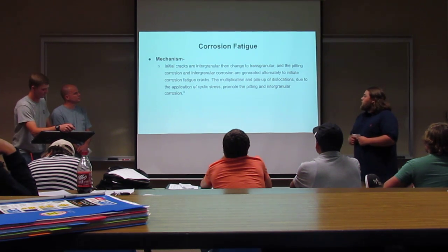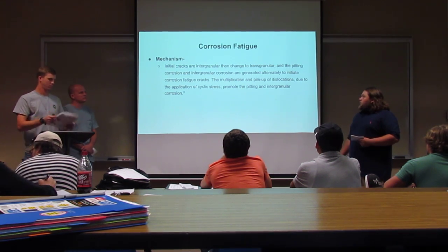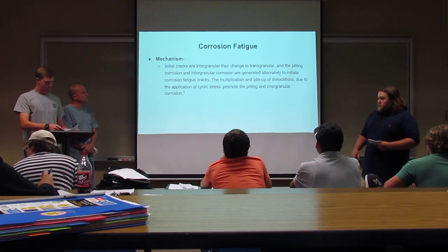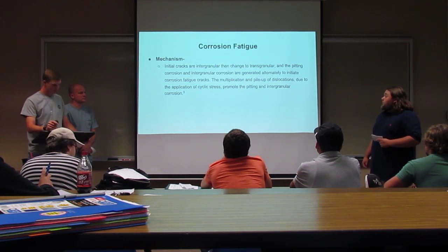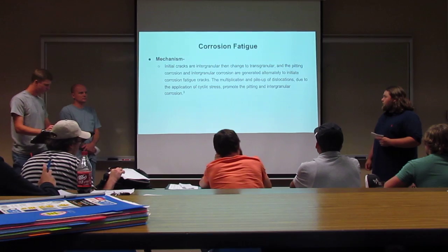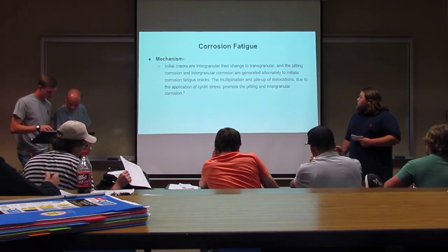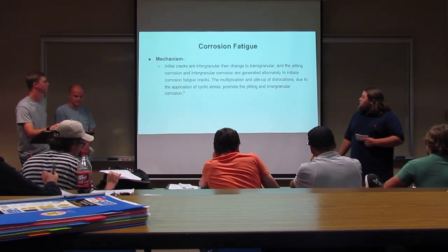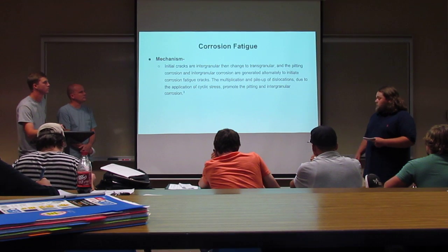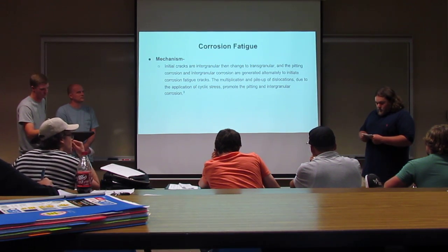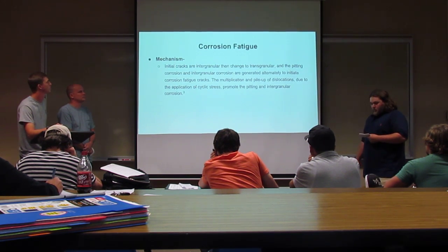Mechanisms. The cracks can be intergranular and change to transgranular. The pitting corrosion and intergranular corrosion are generated alternately to indicate corrosion fatigue cracks. The multiplication and pileup of dislocations due to the application of cycle stress promote the pitting and intergranular corrosion.